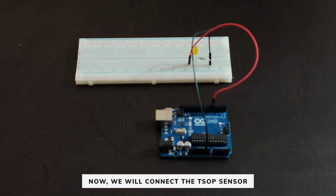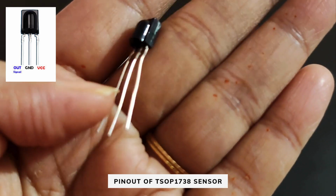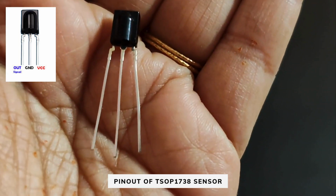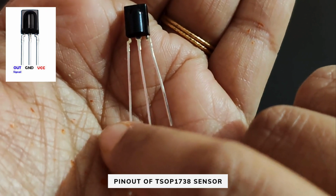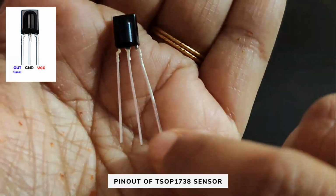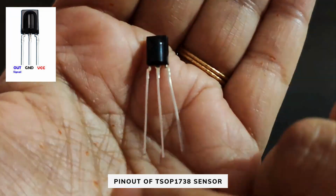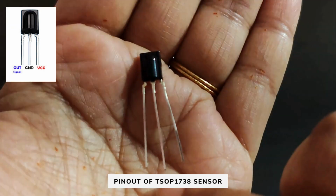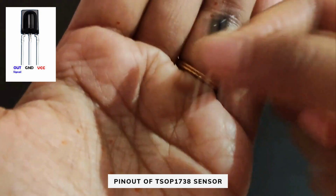Now we will connect the TSOP. This is the TSOP. If the curved surface is facing towards us, then the left pin is the output pin, the middle pin is the ground and the right side pin is the VCC. So we will connect the output pin to pin number 3 of the Arduino, the ground to the ground pin and the VCC to the 5-volt pin of the Arduino.